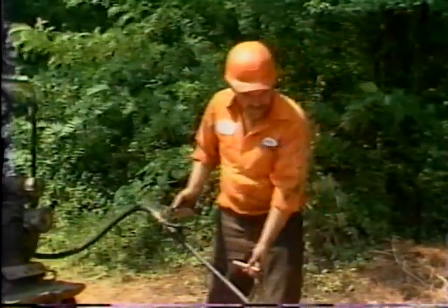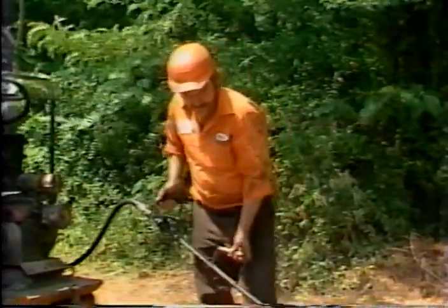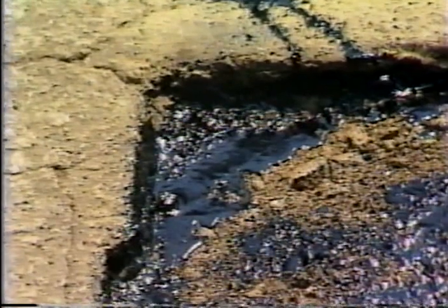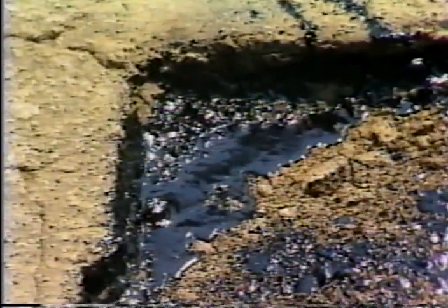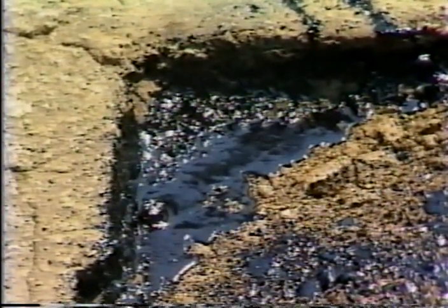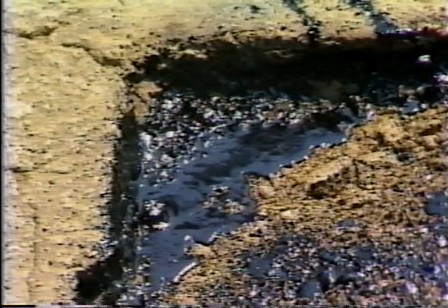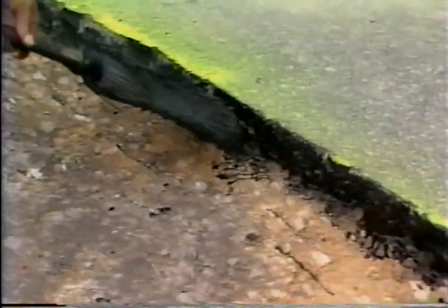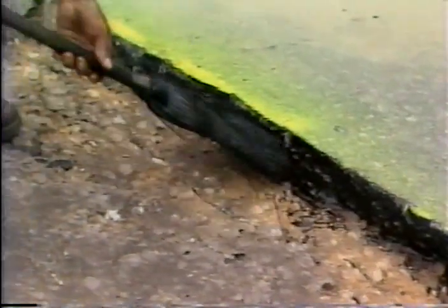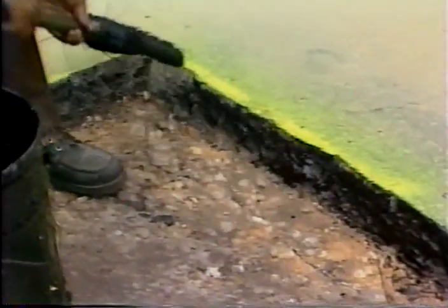The best method of applying tack is by spraying. This provides a thin and uniform coating. Pouring is not recommended because it results in an accumulation of excess asphalt at the bottom of the hole around the edges. If a tack coat cannot be sprayed, brush it uniformly onto the sides of the patch area.